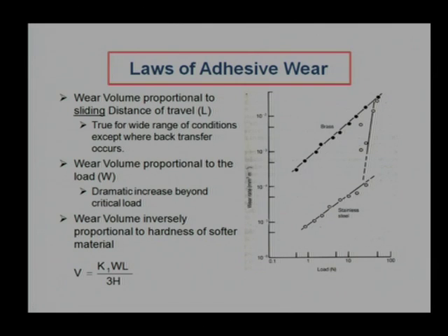This sudden change in wear rate generally occurs because of the deformation or removal of the oxide layer. Assume that initially the stainless steel has some sort of contamination layer, and after a certain load is applied, that layer is deformed, fractured and removed from the surface. Then there is a jump in wear rate.